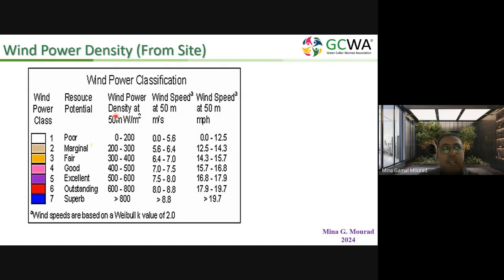We mustn't put the probes on towers with a height of 100 meters. You can just measure the wind velocity with probes or anemometers at 50 meters height, or 25, and then in the next slides we will see how we can calculate according to the geographical obstacles that exist here at the site.